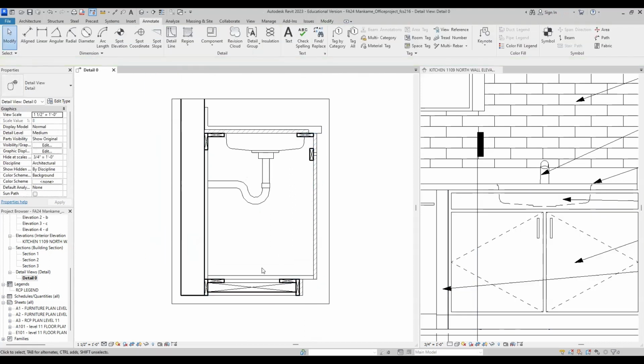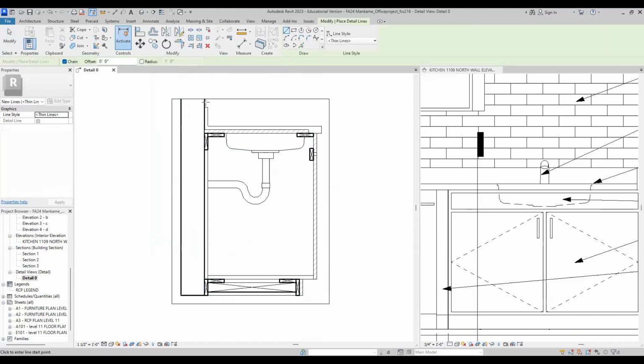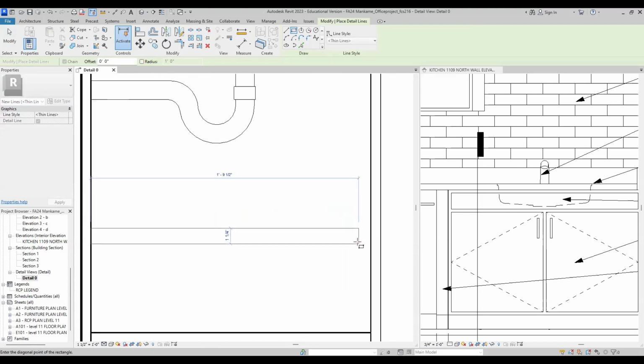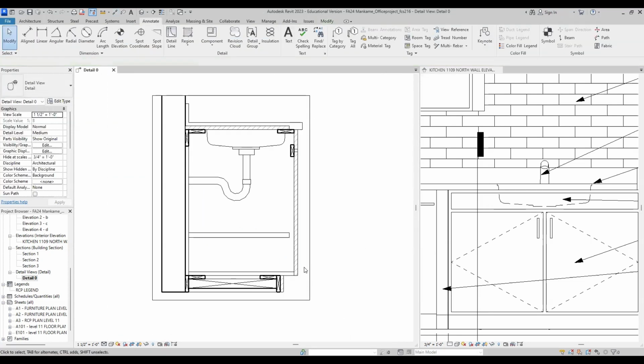I have all these details. Now, if you see here, you have enough space below. If you want to add a shelf, like a floating shelf or adjustable shelf, you can add, or if you want to just do that, you can keep it that way. If you want to add adjustable shelving, how you can add, it's up to you. So what I will do, I will just draw it. You can just remove if you want to. Let's see, 1 inch. Yes. I'm just showing you how you can use the casework. You can just delete that if you don't want.